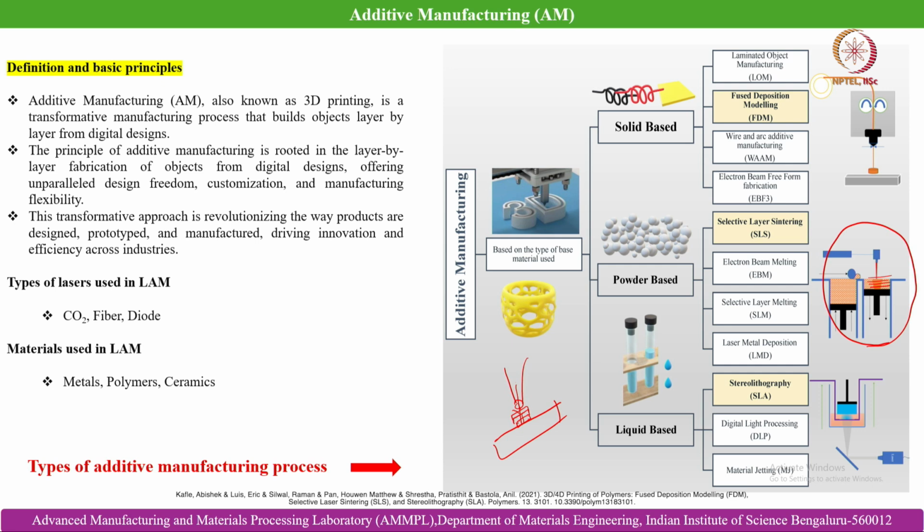So, it depends again, like I told you earlier. Manufacturing is all about making a choice based on the problem at hand. It depends on whether you are going to do additive for a repair work or a cladding work, or you are going to build a micro part with complex dimensions, where conventional manufacturing can become very costly in terms of die manufacturing, in terms of machining techniques, etc.